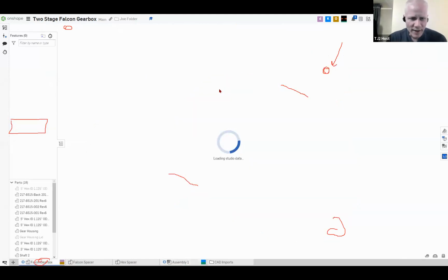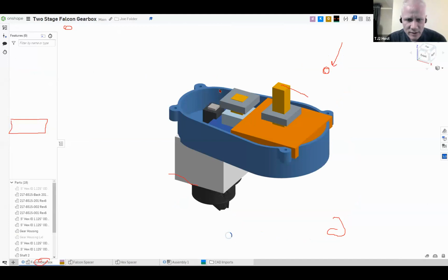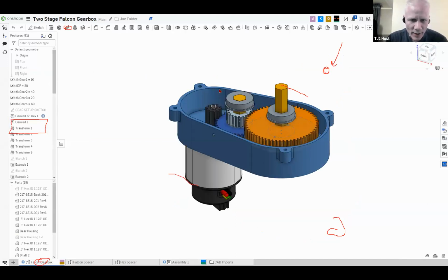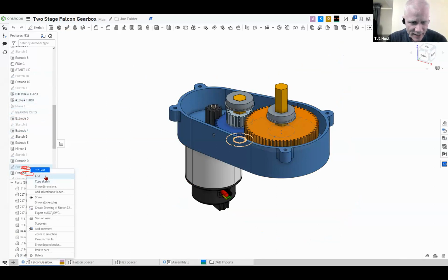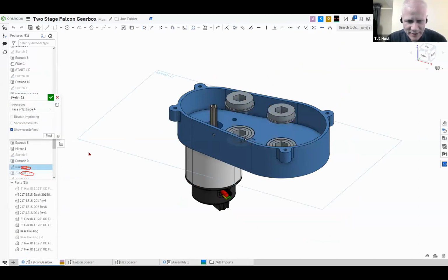Yep. And then we can do this, if we find out where we made this guy. If you just click on that surface right there, it'll highlight in the tree where we made that. We extruded it right here, right? So let's edit the sketch, the one above that. Click on that guy and edit it. And let's just put like a 16th hole.